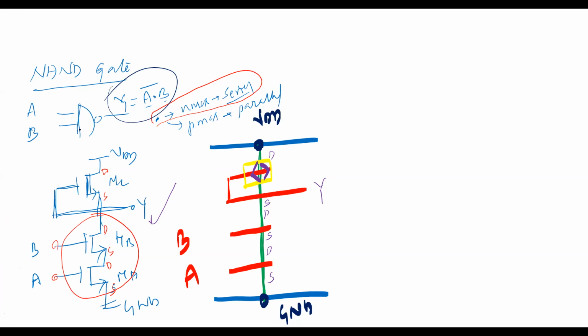In CMOS, both NMOS and PMOS devices are there in equal number. Clear? Yes, sir. First I will start with the NMOS devices. Since it is a dot product, NMOS devices should be connected in series. So this is A. This is one more transistor. Two transistors, A and B, like this, whose source, ground, source, drain.